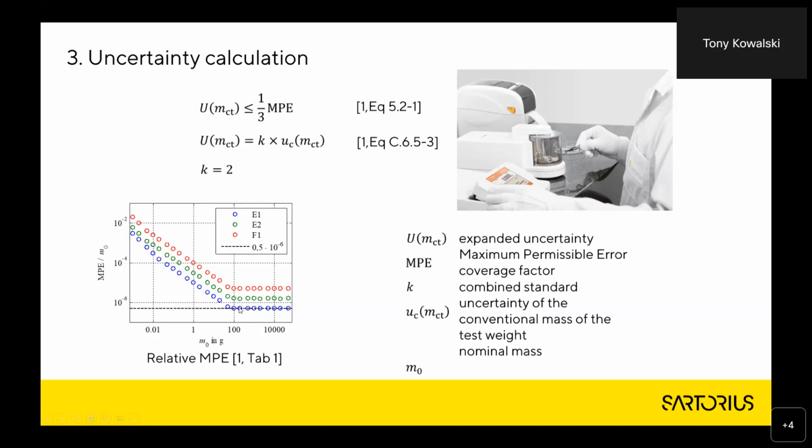So it's a fixed value which is almost negligible at the higher end. We would never use a 10 kilogram comparator to calibrate weights in this range, because the uncertainty contribution, as you approach the lower part of the range of any mass comparator, has a bigger influence against the small weight that you're comparing. So for weights of this value, we would have a comparator with maybe 50 gram maximum, and the contribution of the uncertainty then is lower.